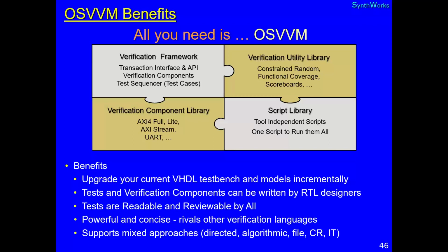It's powerful and concise. And as far as conciseness and capability, we rival other verification languages like SystemVerilog. Okay, so SystemVerilog is not the only answer. In fact, OSVVM gives you all of these features on an ordinary VHDL 2008 simulator. So you're not paying incremental licensing fees like you will with SystemVerilog. And we support mixed approaches, very straightforward in our test cases.